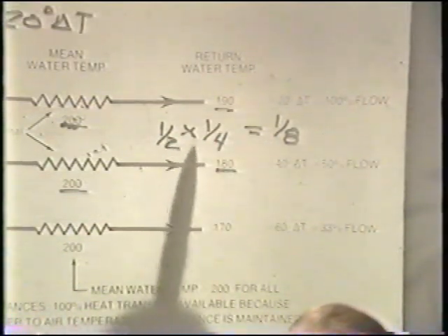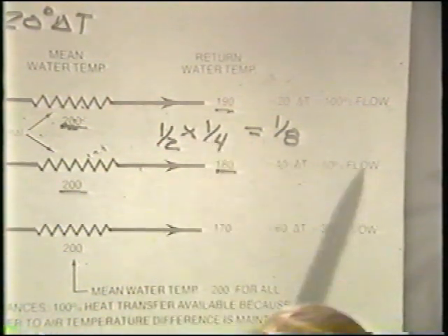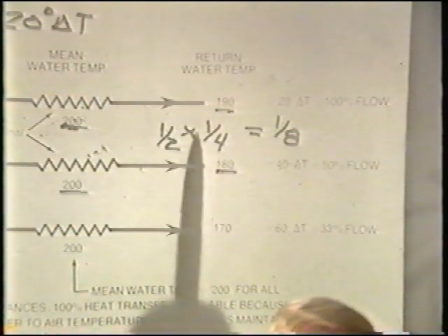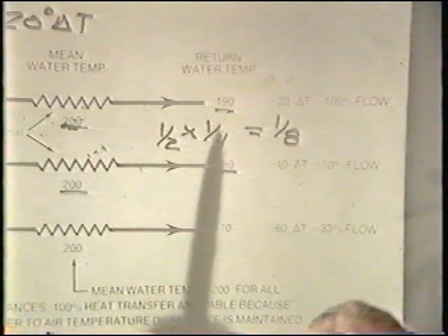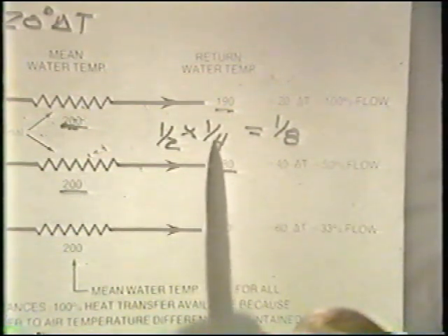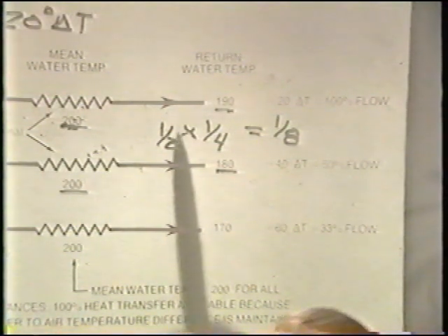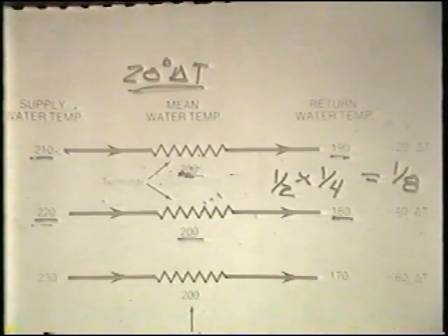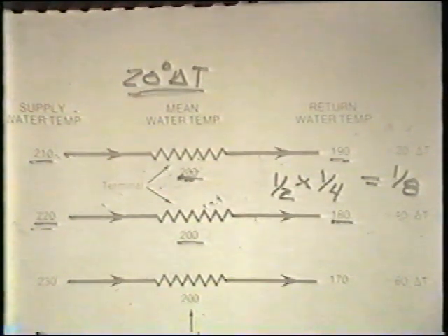The reduction of flow rate in the existing piping systems works well, but we must concern ourselves as we modify these existing systems to decreased flow rate with the increased potential for trouble through flow balance. Providing we provide the necessary flow balance in the existing system, we will work quite well. It should be remembered that the 20-degree temperature drop design system overcomes, because of very high safety factor, a good deal of trouble potential from a lack of flow balance.